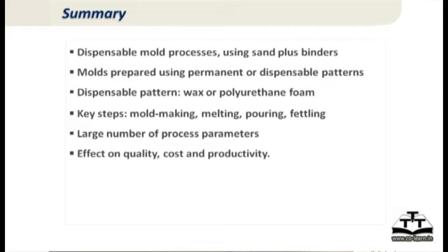What we want to emphasize here is that even this basic overview of the casting process would have given you a clue that there are a large number of parameters: material parameters, not only of the cast metal but also the mold material, core material, and other elements used in a mold, which we'll see later, plus your process parameters for melting, pouring, molding, and finally your end processes like heat treatment and inspection and so on.